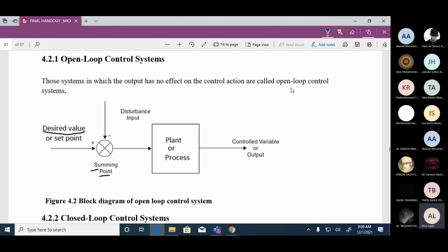So we are calling this an open loop control system. Why? Because there is no check for measuring. We are only switching on the heater or switching off the heater. It's only going by on and off. There is a decision according to which the plant is going to work, but we don't have any way of taking a feedback. There is nothing that is going back. Now, what is another example of an open loop control system I can give you?